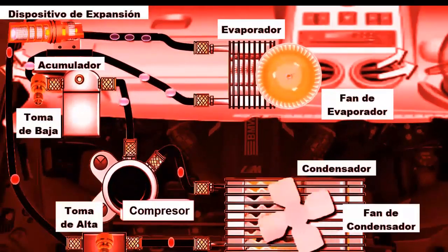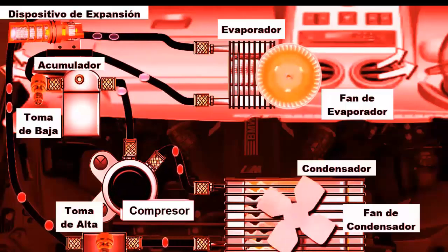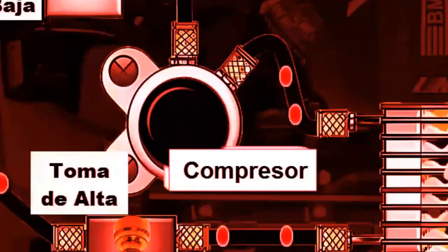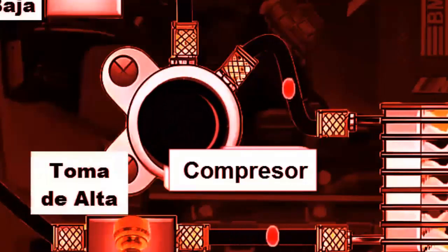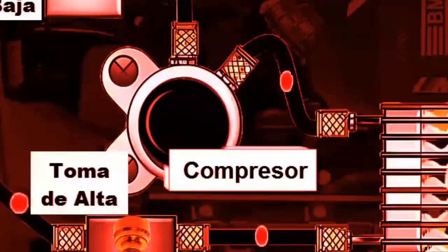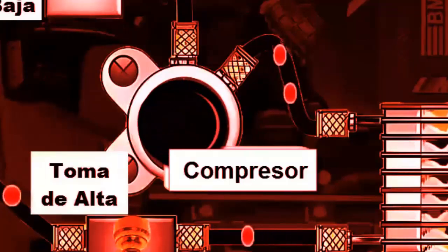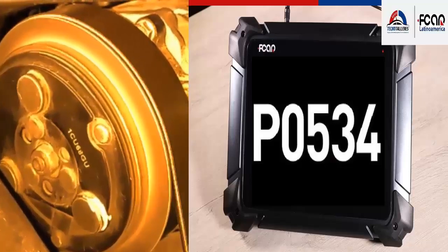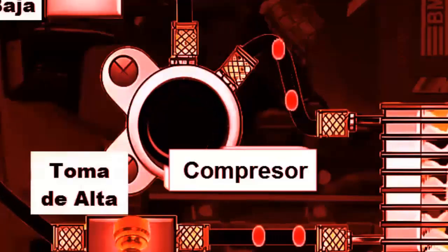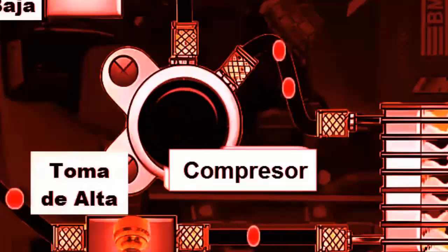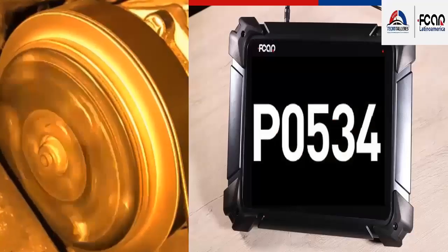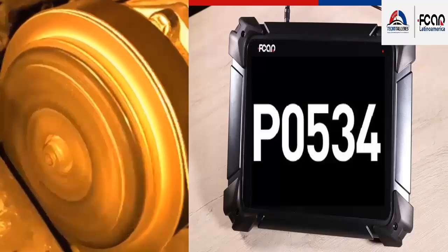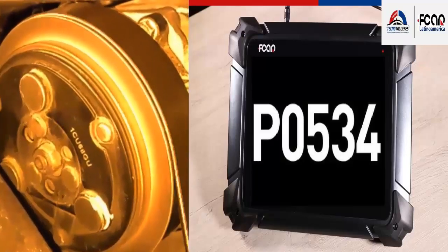2. Compressor not working. The compressor clutch should engage with a click when the air conditioning is turned on. If the refrigerant level is too low, a pressure switch or pressure sensor stops the compressor, preventing it from functioning correctly. 3. Intermittent compressor activation. If the clutch engages and disengages constantly, this may be due to low pressure in the system, which disconnects the compressor to protect it from low pressure.